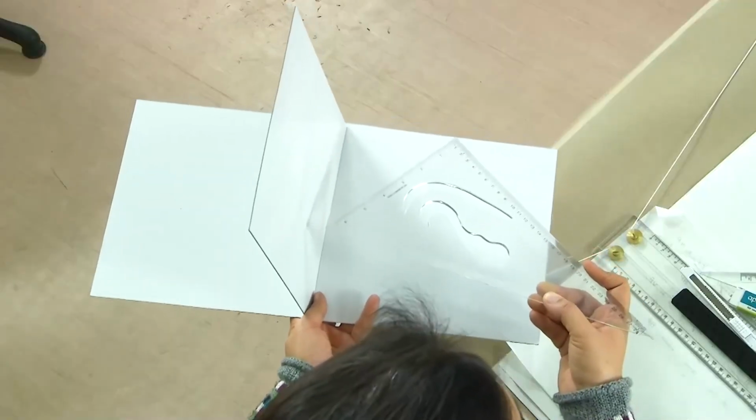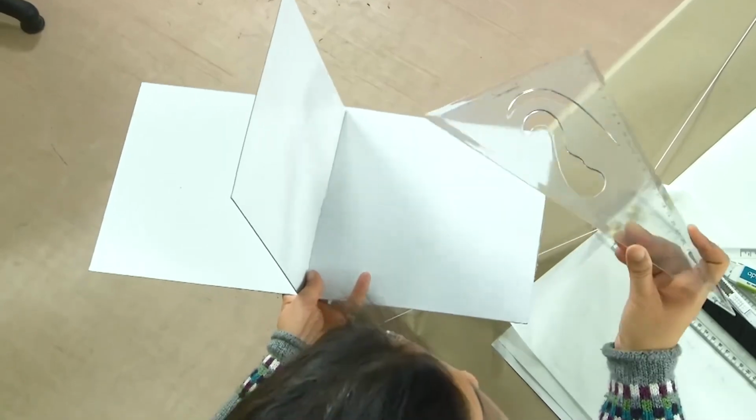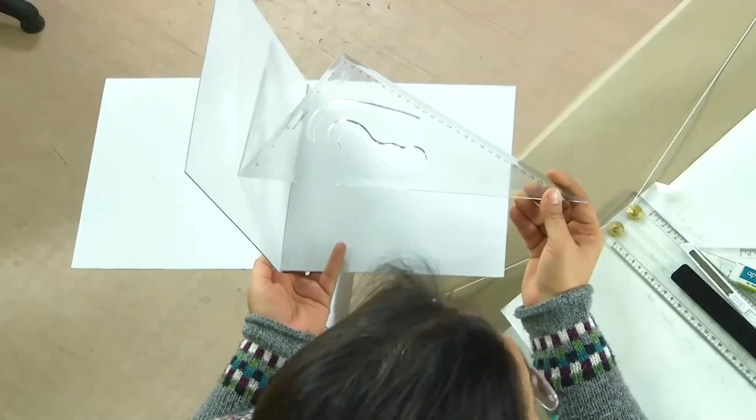Now, how are these 3 lines placed? The plane entirely is parallel, but this line could be making an angle with the VP and parallel to HP. Similarly, the other 2 lines. The given condition is that all these 3 lines which constitute this plane are going to remain parallel to HP. So, we will see the true dimensions in HP and some skewed, diminished dimensions in VP.